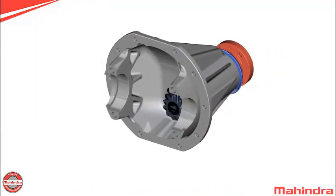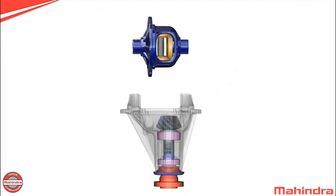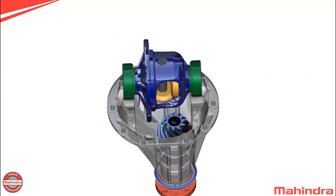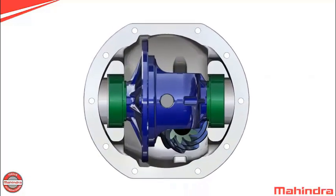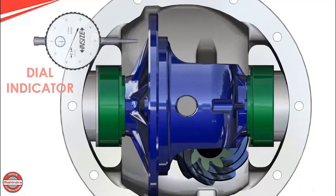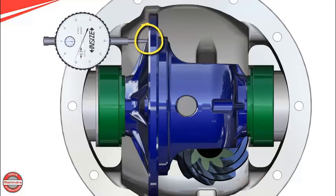Take differential housing with pinion. Locate differential assembly along with dummy bearings 0502 CAA 0001 ST, without ring gear and shims, in the differential housing. Place dial indicator with magnetic base on housing. Locate the tip of the dial gauge indicator on the surface of differential assembly parallel to the housing top and perpendicular to the differential case flange.